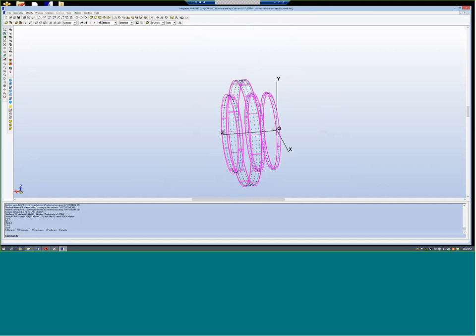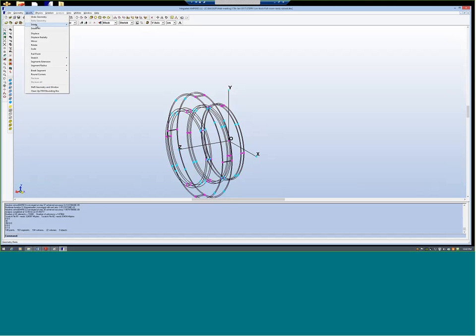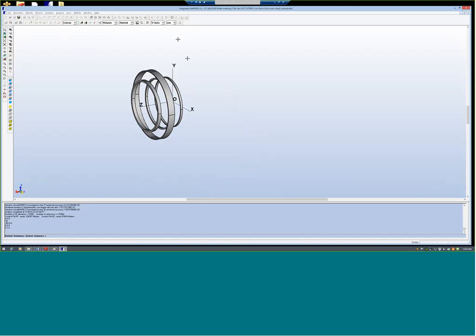Because I want to apply an anti-symmetric condition at y equals 0 also, my problem must be only in the region y greater than or equal to 0. So modify, delete volume. Now this time make it volume here. All this part can go. I should not have it. Remove this.